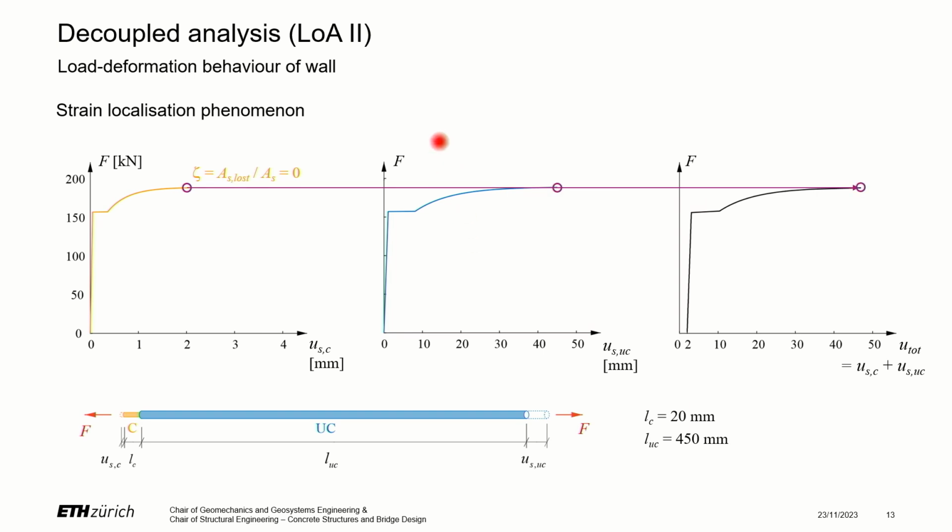So we first start with the case where we have no cross-section loss. In this case, the orange part carries the same load as the blue part, and then the elongation for the whole bar can simply be summed up. If we have then a cross-section loss, this curve here is scaled downwards, and the maximum load is then decreasing. However, this orange part is still at the same ultimate elongation. This is then not anymore the case for the blue part, since the maximum load decreased, and this blue part will then carry only part of its maximum load and then also show smaller elongations.